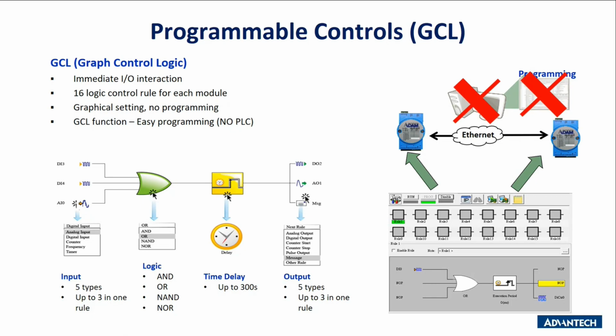But also take note that our response time for this is 100 milliseconds at minimum, which is not comparable with PLC response time, which is normally in microseconds. And the logic control has to be based on actual physical signals, unlike programming, where they can remember the previous state.